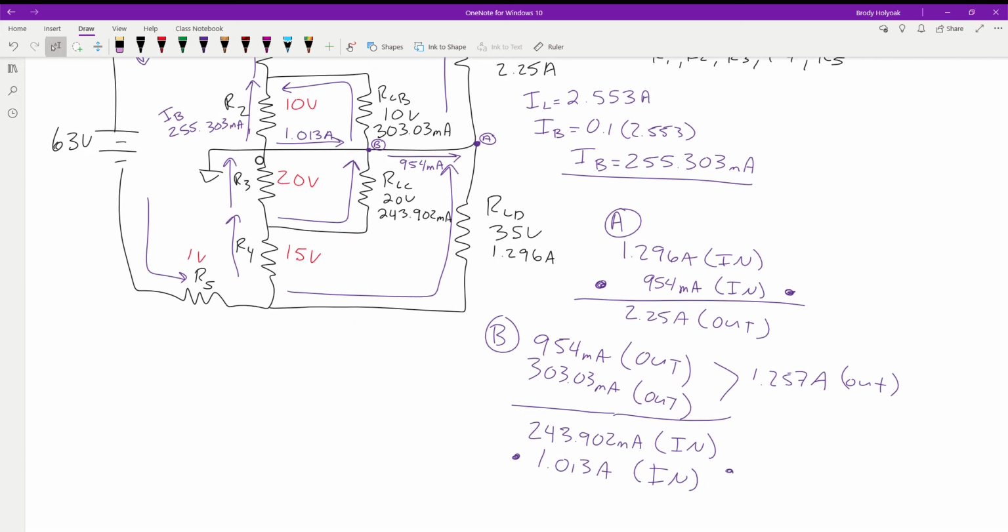So the next step, like I said, we want to look at where do I have the information to solve where these are at? Because we know that the currents have to be equal, going into a node and going out of a node. So we're going to move over here to connection C. So at point C, we have 4 connections. We have the ground, which we're not going to have any current flow, so we don't have to worry about him. We have 3 connections.